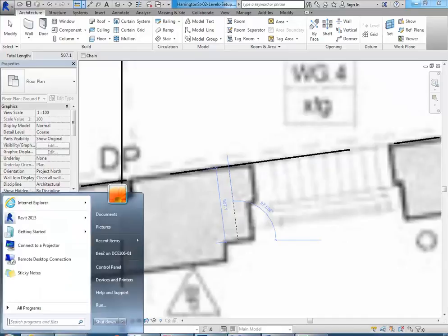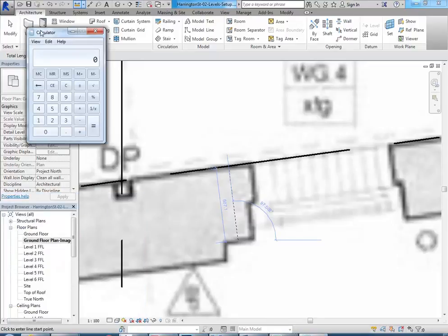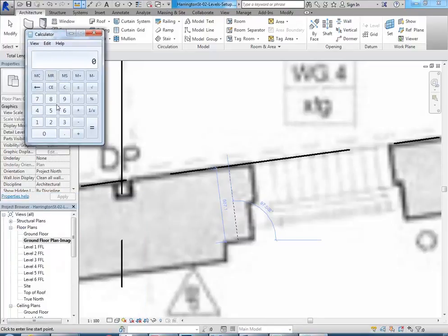500. So let's do a bit of calculation first before going madly ahead and just creating the walls. Just to try and get an idea of what the construction is. You don't need to have this totally worked out, but you won't have an idea. So solid brick wall, do you know how thick that is? Yep, exactly. Yeah, with no cavity. Not far off, yeah, 230. Yeah, so 230 is a solid brick wall.